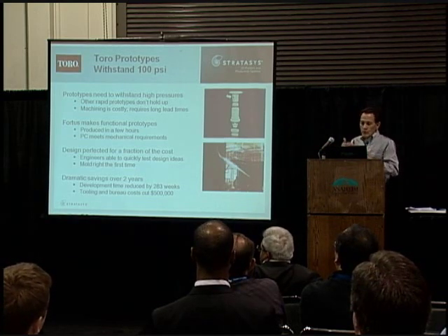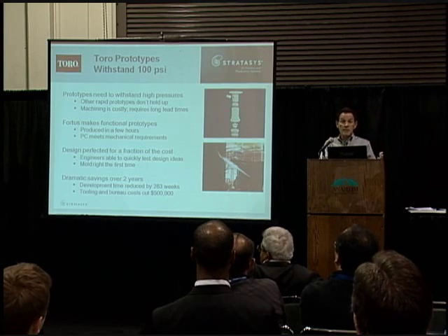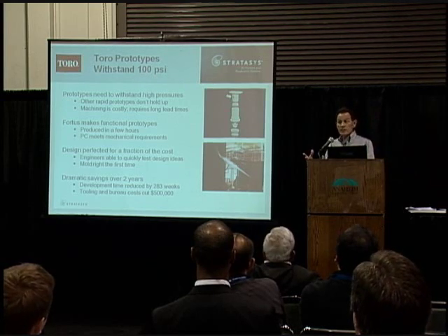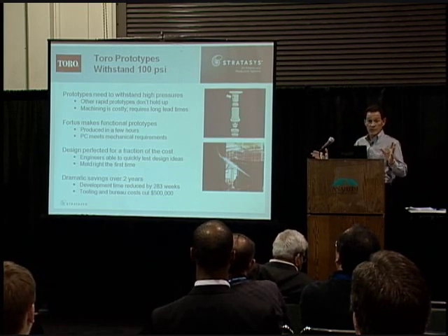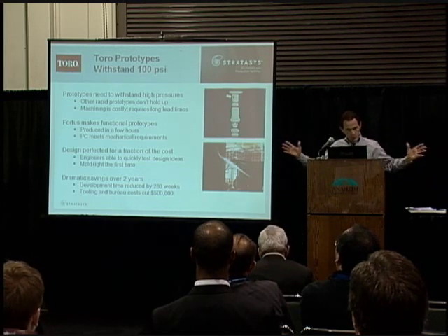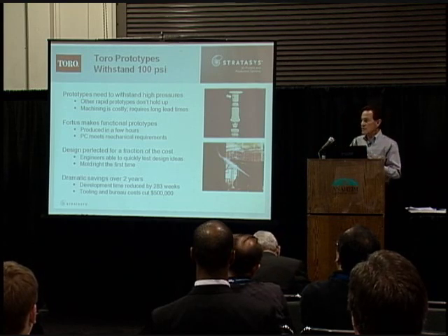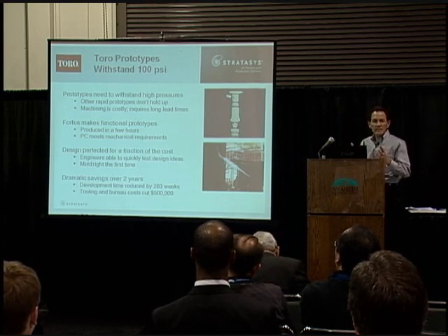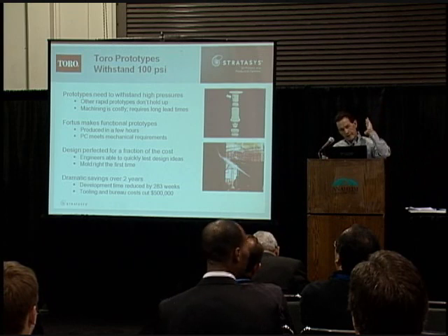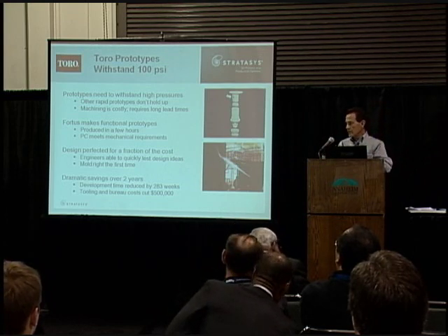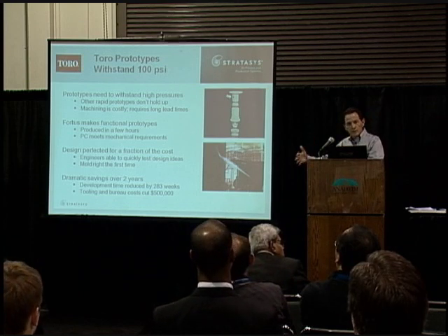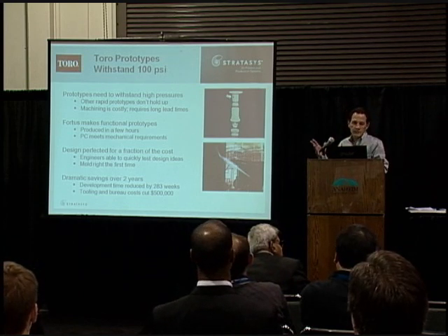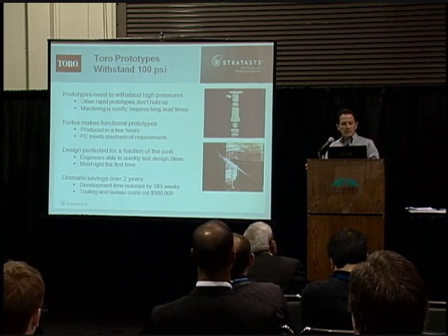We went through and found out not only could you do the concept models, but with some of the materials, they could actually functionally test and eliminate prototype tooling. What did that do? Reduce the time, reduce costs. They were doing more testing, and they have an indoor test range, 100, 200 feet, where they blast these things off. So they were having to wait for tools, make tools, shoot a prototype, go, oh, that's wrong, and go through that cycle.